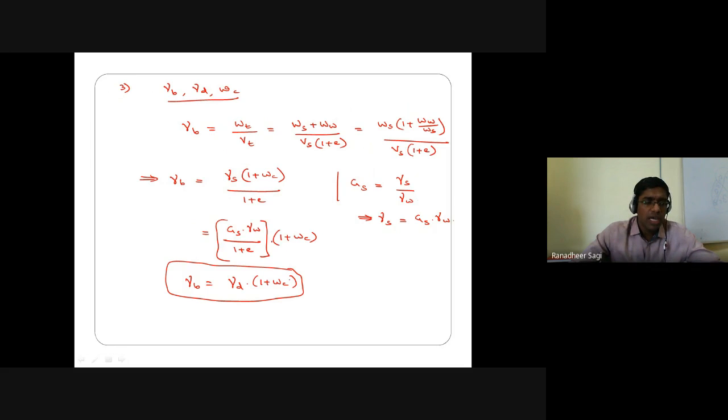And in the same way, I can further go on to find out a relation, not just in terms of what I have represented as bulk unit weight, dry unit weight, and water content. I can also further rewrite those terms according to the necessity and derive the other parameters. Like say, if I wanted to derive a relationship between bulk unit weight, void ratio, specific gravity of soil solids, and degree of saturation. Likewise, if I want, I can still do that. How can I do that?